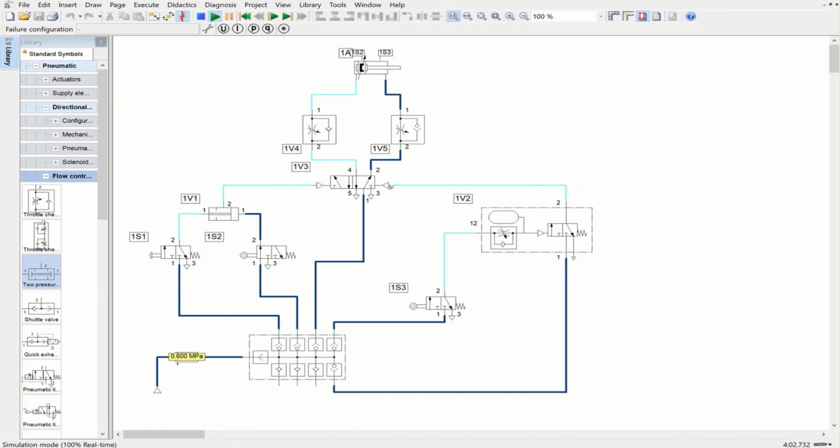And it reaches the fully open condition, but it should stay there for a few seconds, because if it returns back immediately to the closed condition, right, we cannot pass through that door safely. So we need to have a sort of time delay valve. Generally, this automatic door system is a sort of electro-pneumatic system, but we can design an automatic door with the use of just a pneumatic system.